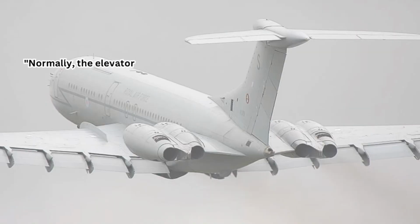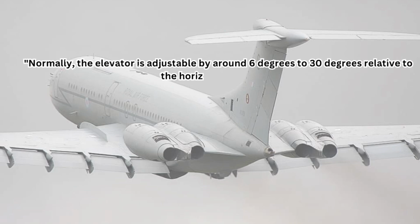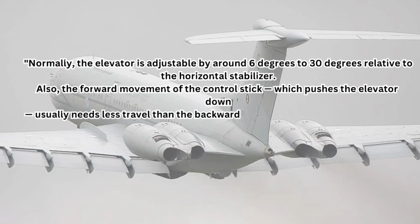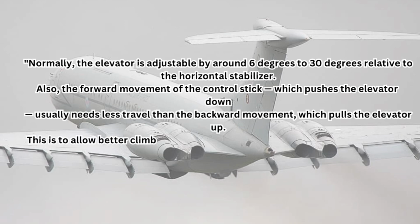Normally, the elevator is adjustable by around 6 degrees to 30 degrees relative to the horizontal stabilizer. Also, the forward movement of the control stick, which pushes the elevator down, usually needs less travel than the backward movement, which pulls the elevator up. This is to allow better climbing control, especially during critical flight phases like takeoff.